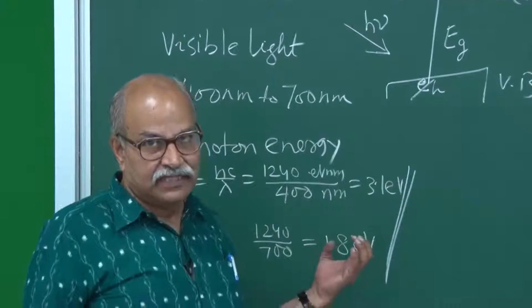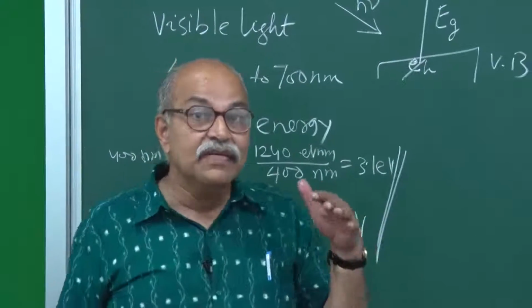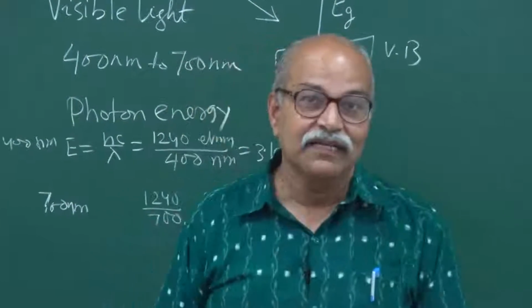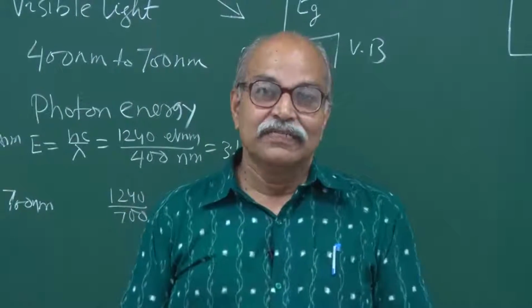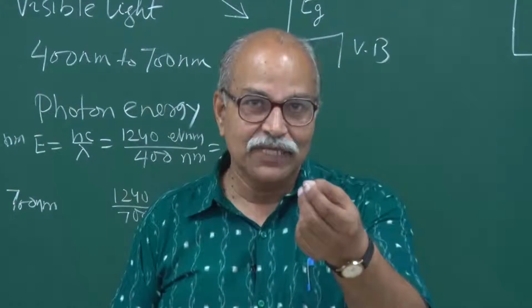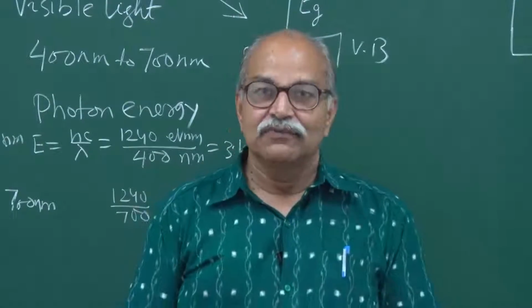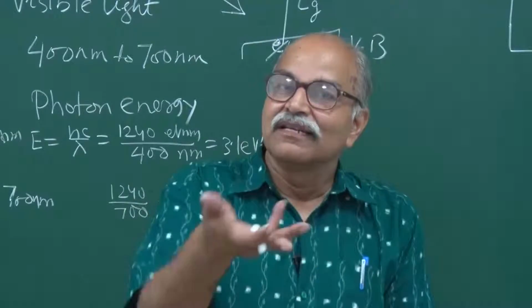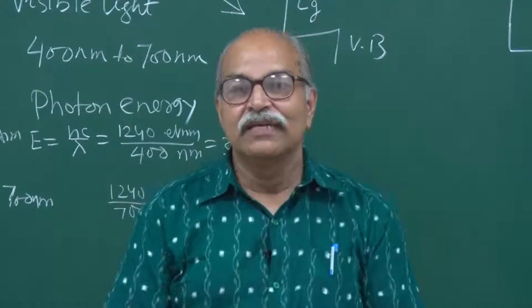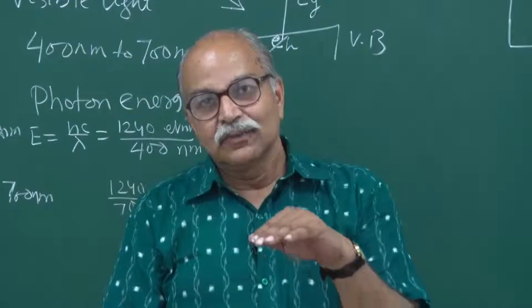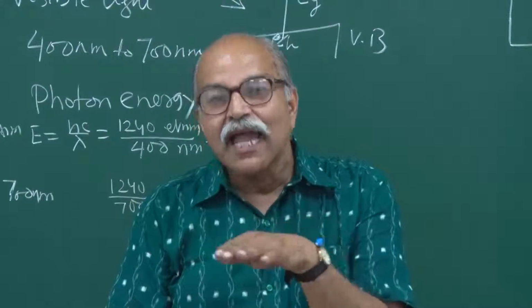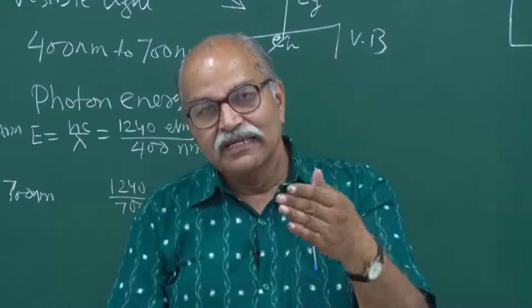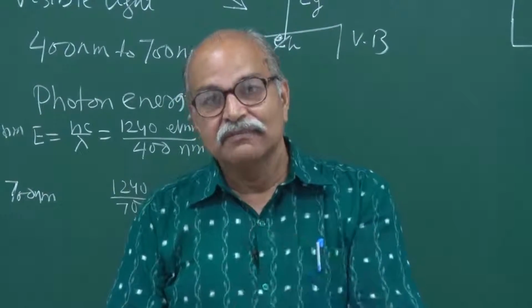or if it is to be used in this fashion, we call it photodetector, and then light has to reach this depletion region. So, that has to be taken care of in fabrication. All this junction, if I showed you that rectifying diode, is all covered in that blackish material. So, light will not reach the depletion region. So, here it is constructed so that you have a transparent cap on this junction, so that light from outside can go and fall on this material.